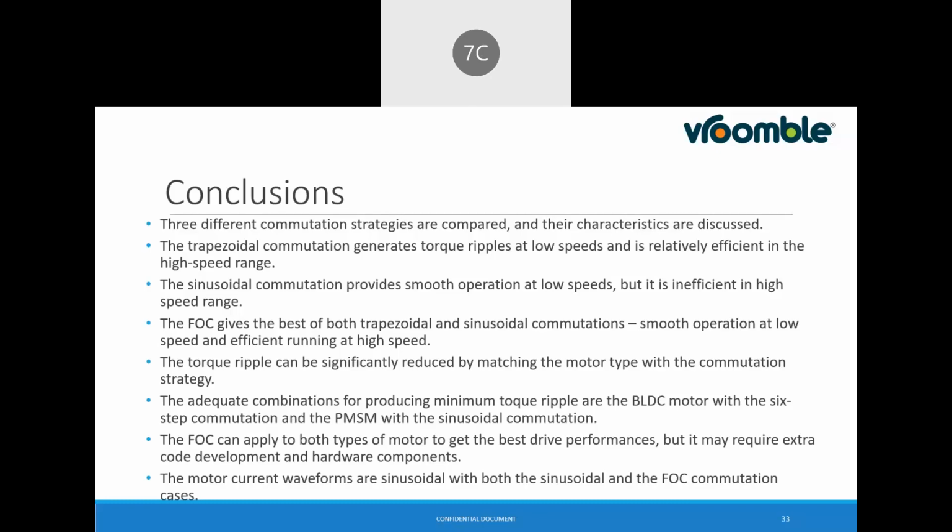Yes, earlier the Tata Nexon and the earlier Mahindra e2o were induction motors. Even earlier Teslas were also induction motors. You can check the Tesla Model S and Roadster. They were using induction motors, right? With an induction motor, DC power can be converted into AC, that is for sure. But you don't get instantaneous torque like you get in a PMSM motor with a magnet.